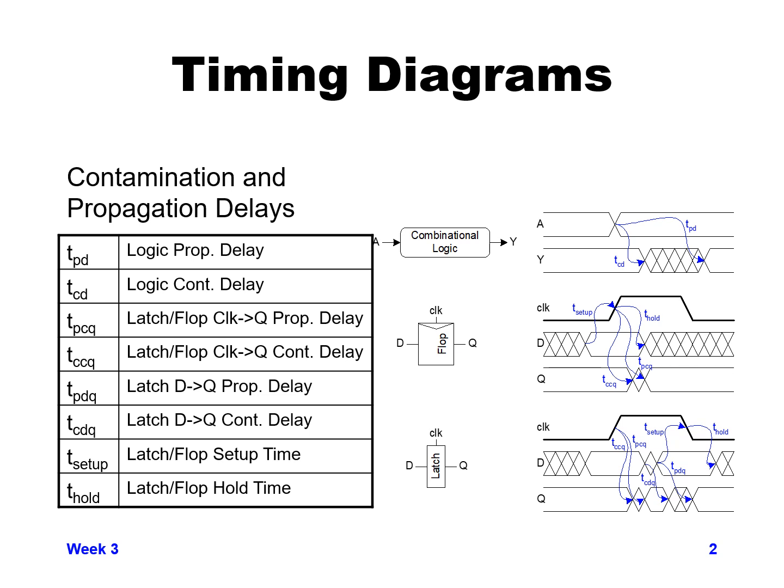So let's go through a number of different types of delay that we have to concern ourselves with, from the standpoint of looking at combinational logic versus flops versus latches. In combinational logic, it's maybe the easiest thing to look at. We have what we've called in the past a logic propagation delay. That's the longest amount of time it takes, when a signal at the input of the combinational logic changes, till the output becomes stable again.